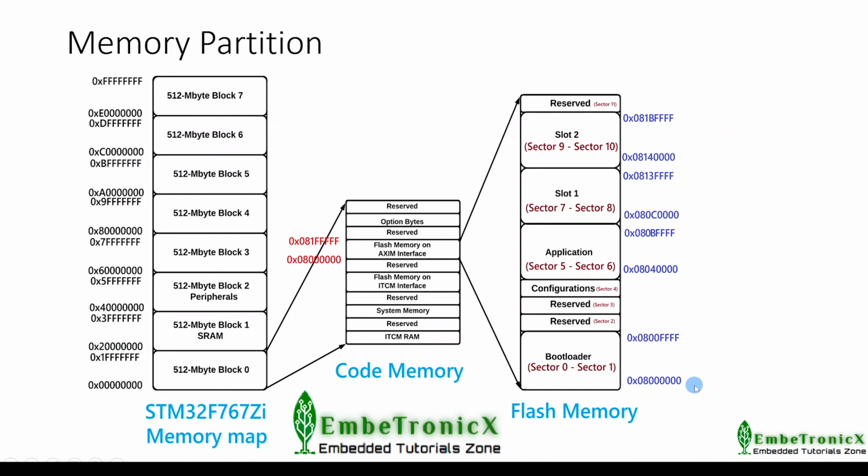That's why we are writing our bootloader to that memory and the processor will read that memory using the ITCM bus. For understanding, you can assume that 0x00200000 is the alias of 0x08000000. If you want to verify this, then write the bootloader into 0x08000000 and read 0x00200000. The same data will be present in both addresses.